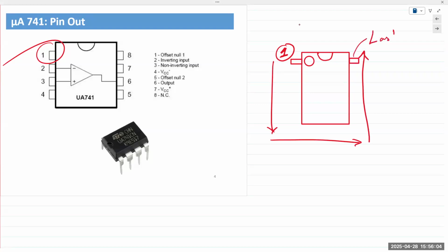That's the last pin. Again, whether it's 8-pin, 14-pin, 16-pin, 20-pin, 48, 100-pin IC, doesn't really matter. The pin out configuration is always like this. Start from the left, go down, make a U-turn, and then go up.